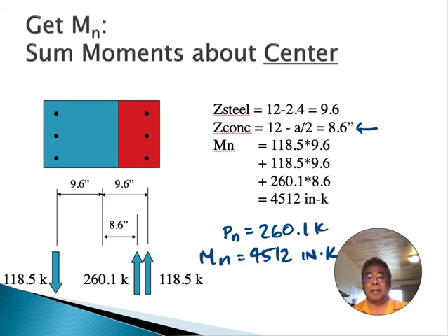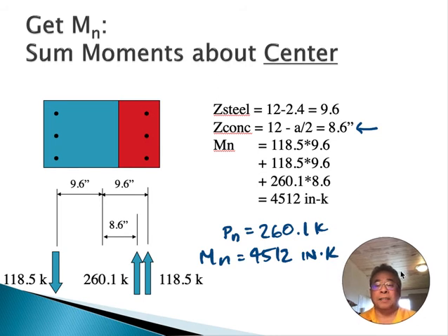Okay. Now, this was for a neutral axis located at 8 inches. If you change C, like to 10 inches or to 4 inches, or you can even have 100 inches, these numbers change. And so you will get an infinite number of combinations of P and M that will cause that column to fail.